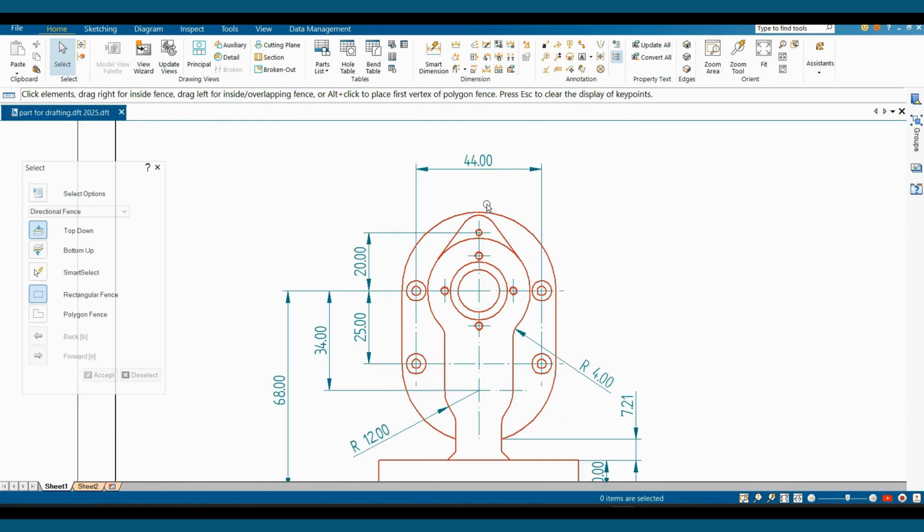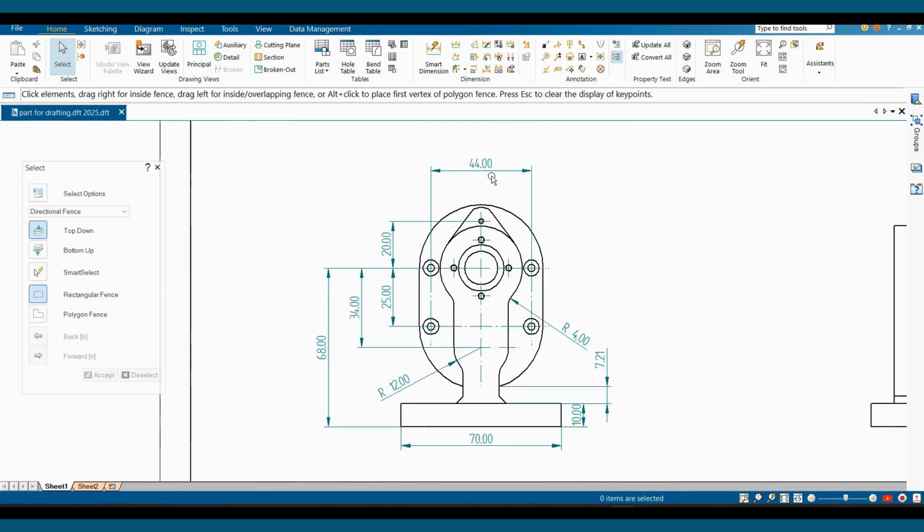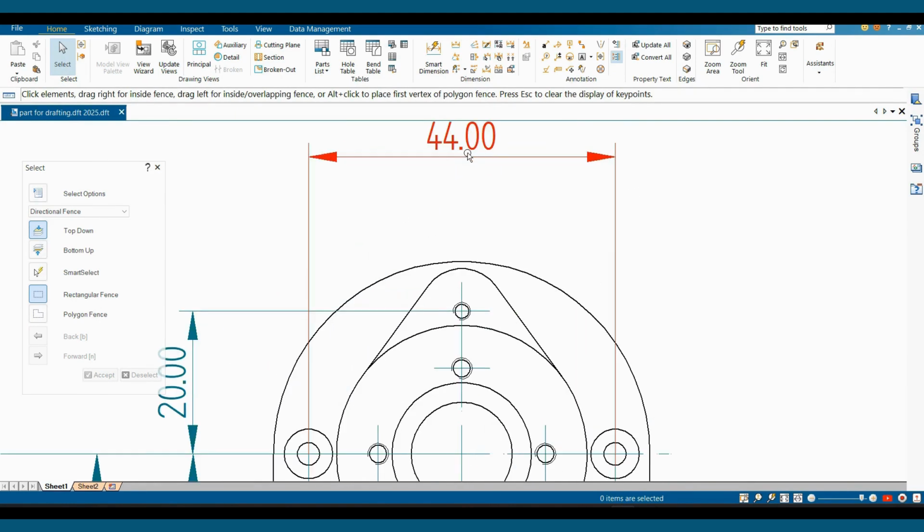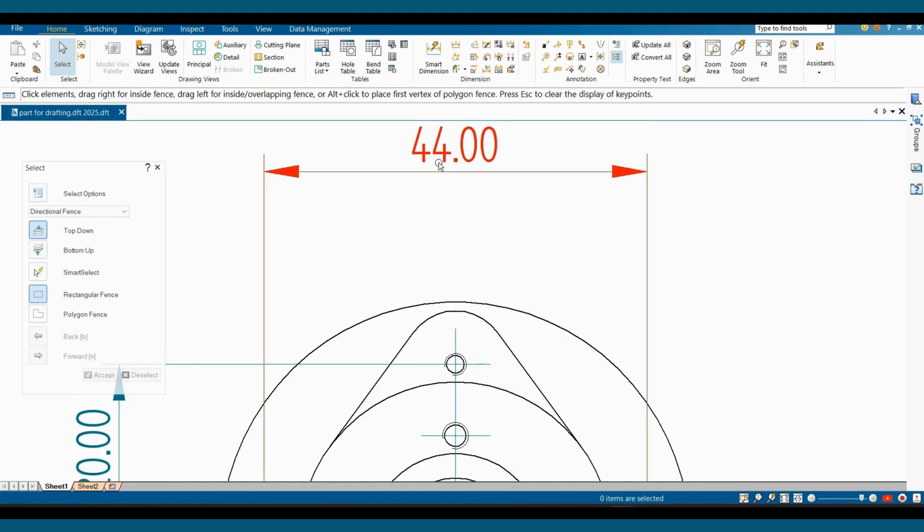So now even if the feature is having round up value, still the zeros are being shown because we have put on the trailing option. As the precision was in double zeros, that's why these are showing double zeros. Now one more thing, you can see here after adding precision values and showing the trailing, the separator is being shown as a point here.